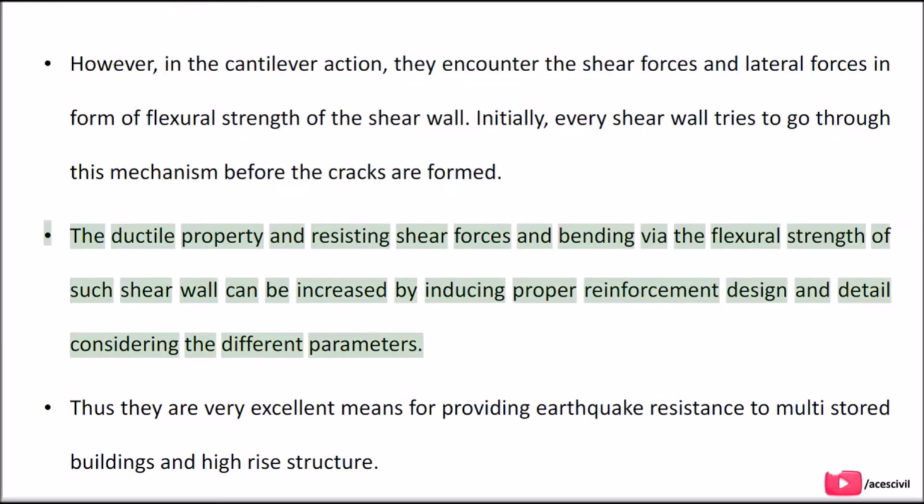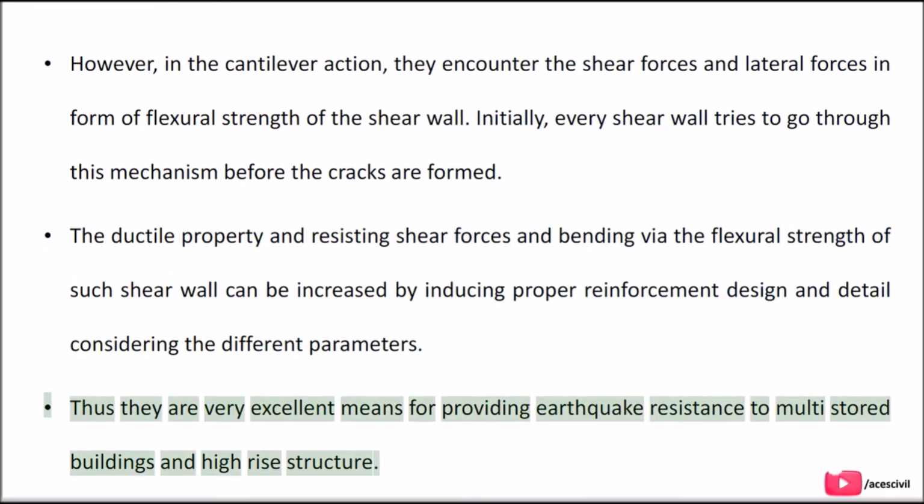The ductile property and resistance to shear forces and bending via the flexural strength of such a shear wall can be increased by proper reinforcement design and detailing considering the different parameters. Thus they are an excellent means of providing earthquake resistance to multi-storied buildings and high-rise structures.